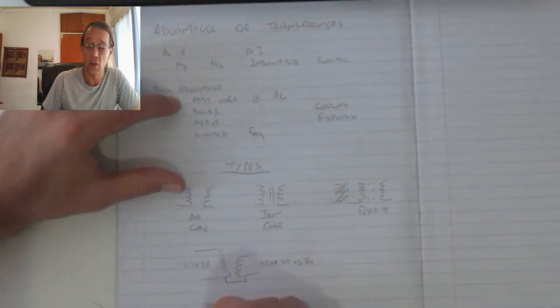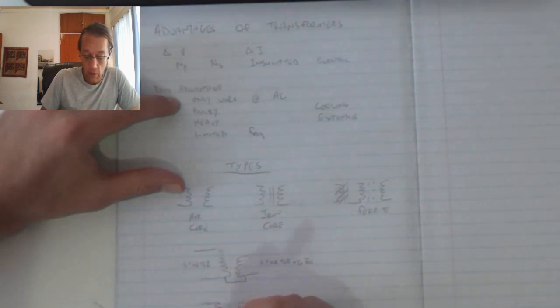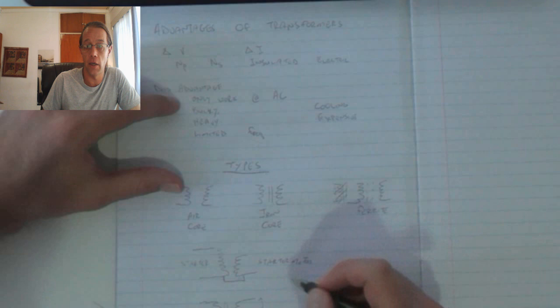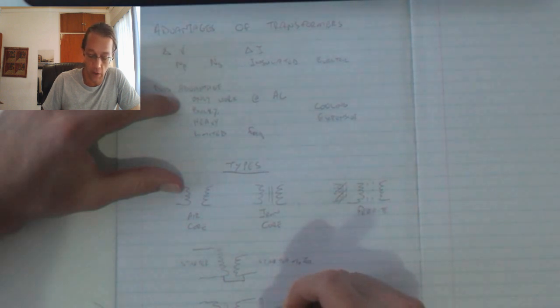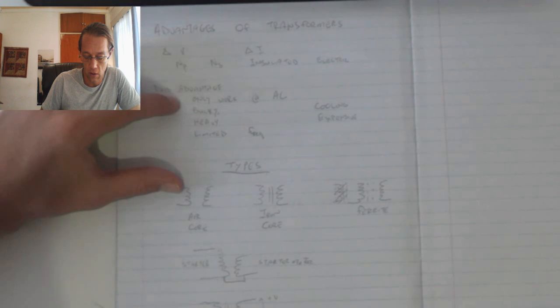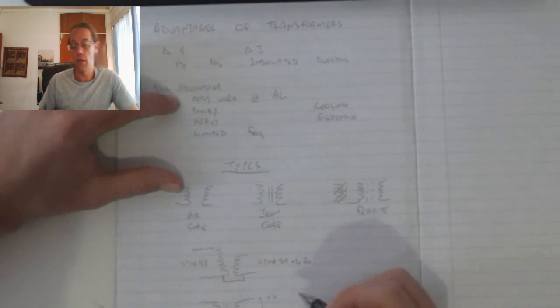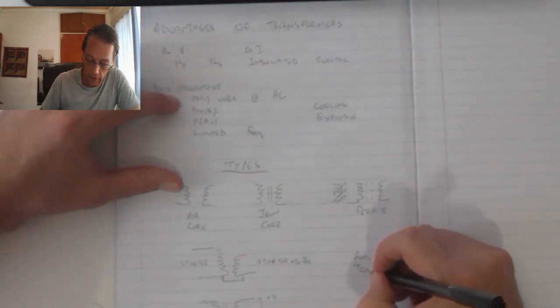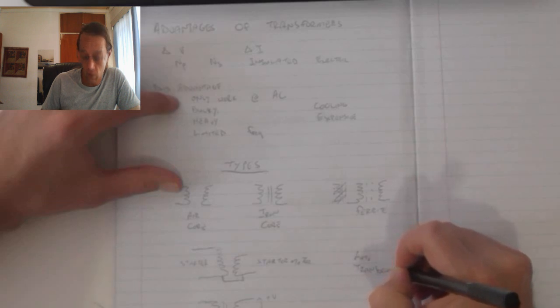My center tap transformer, I've got primary turns, secondary turns, let's say this is a soft iron core, and we've got a tap that connects out in the middle. That means that that voltage and that voltage is going to be equal to each other. The only difference is that 0 volts, and that's plus V, and that is minus V. Voltage will switch. If that center line becomes my reference, this is my part 2 transformer.